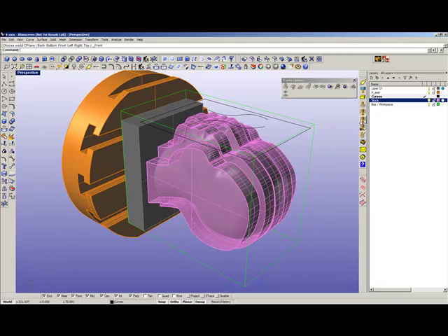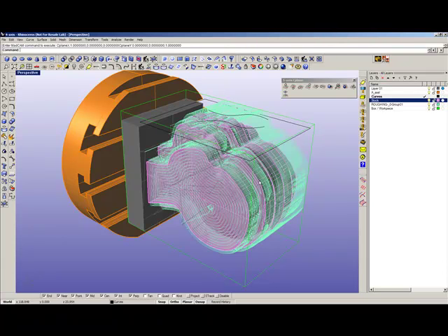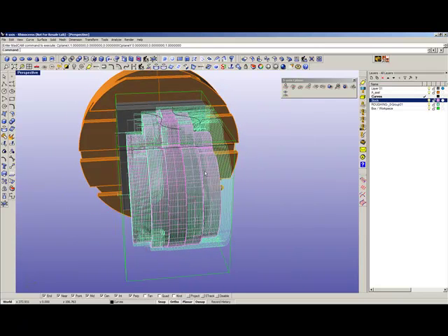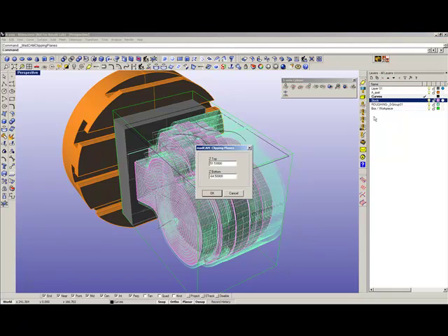and then we can apply a 3D roughing toolpath. And here we can see that the toolpath is going all the way down to the other side, and then we can use the clipping planes to control the depth. So if we set the bottom clipping plane to 0, it will stop at the center of the A-axis,